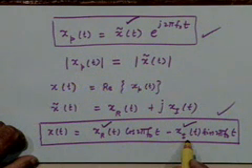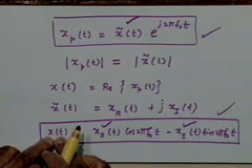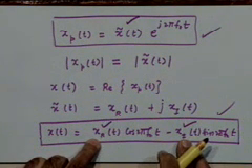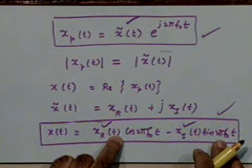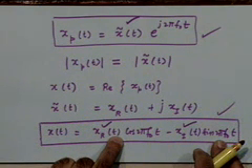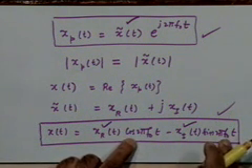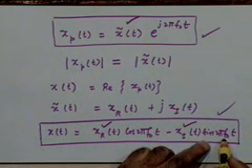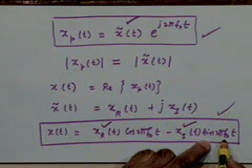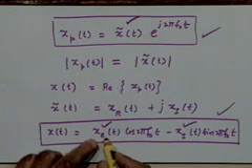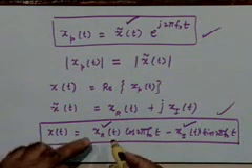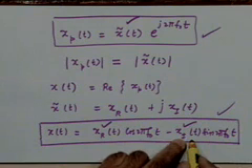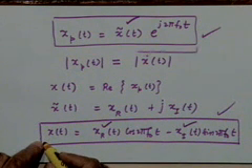So I can represent x(t), the original band pass signal, an arbitrary band pass signal, in terms of two low pass signals multiplied with quadrature components of a carrier. We call cosine 2 pi f naught t the in phase carrier and sine 2 pi f naught t the quadrature phase carrier. And x_R(t) is therefore called the in phase component of x(t), and x_I(t) is called the quadrature phase component of x(t).